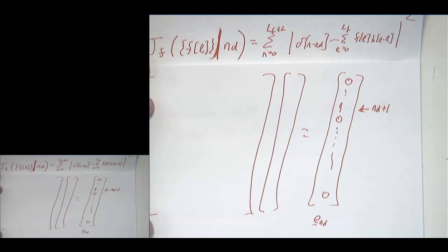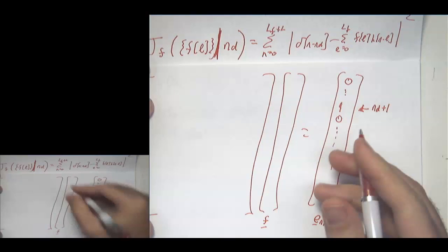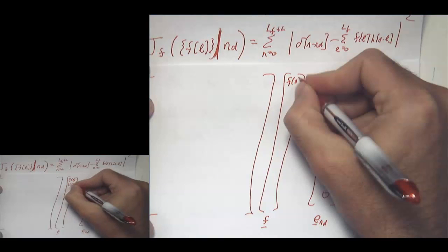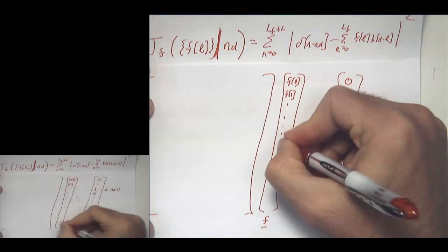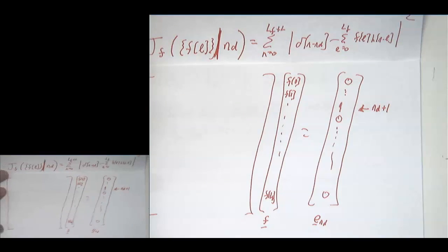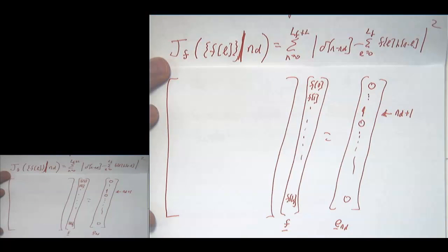Okay, so remember, this is our unknown here. Our unknown is going to be the parameters of the filter f. So we're going to put f0, f1, down all the way through f of LF here. That's our unknowns. And now all we have to do is fill in the terms of this convolution. Now this is a little bit different than the problem that we had before, but you could solve it in the same way.